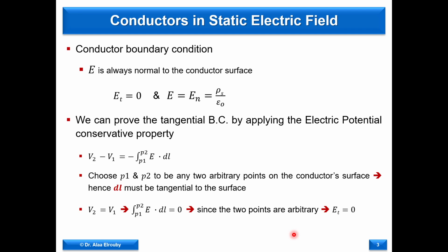At the interface, again assuming the surface of our disk is a conductor, and we are bringing a charge in air close to the surface. The first medium is dielectric, which is air, and the second is the conductor, which is the surface of your disk, and the interface between them is called the boundary between the two media. At the boundary between the air and conductor, there are some rules which we call boundary conditions.